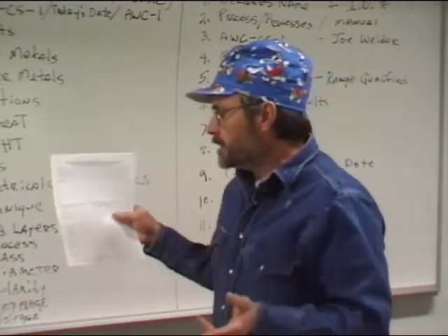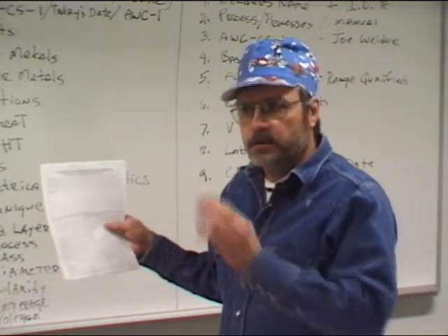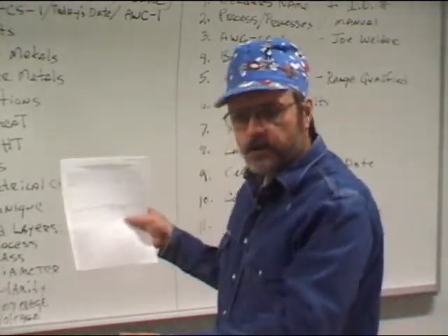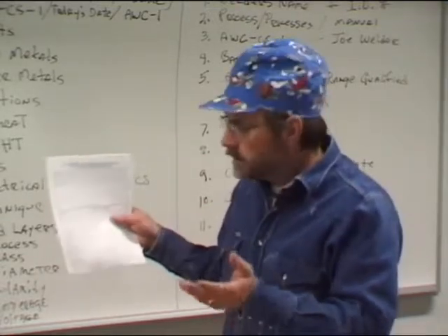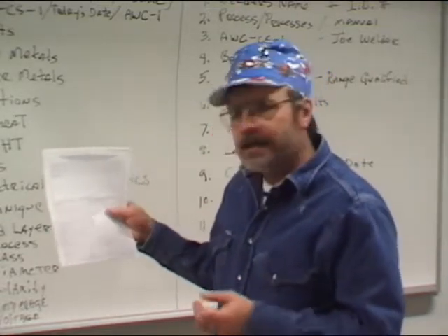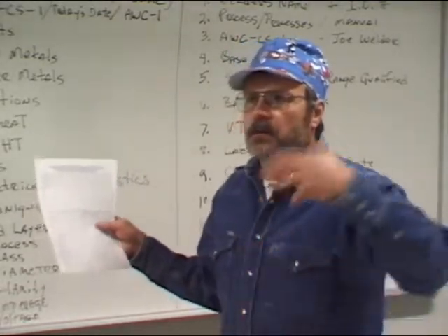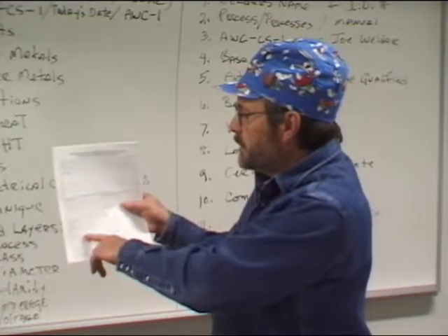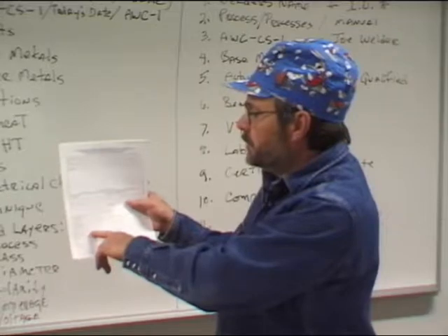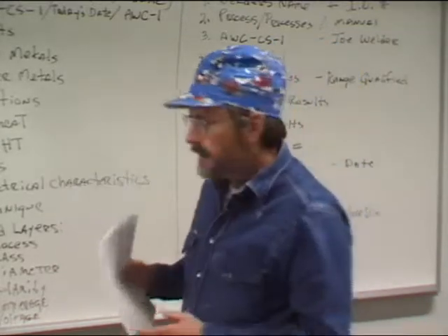A lot of times I'll just leave that blank, but if you really wanted to be accurate about it, you would actually cut a slice of the weld out, and you could etch it with acid and then physically measure how thick it was. But I don't usually get that in depth with these PQRs, especially if it's a PQR that's been done 100,000 times before. So I'll just go ahead and I typically put 1/8 of an inch or 0.125 for the metal thickness on the root pass, and then you have to deduct that. You have to deduct that thickness.